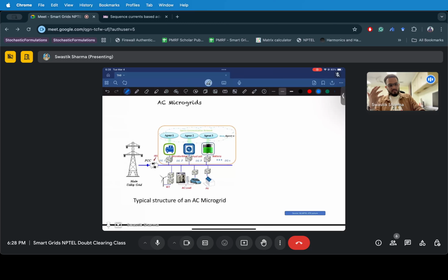They pose certain hazardous situations, for example, if the isolated mode is not derived correctly, you will not be able to tell if you are connected across the utility or not, right? So there are some issues with AC microgrids as well.